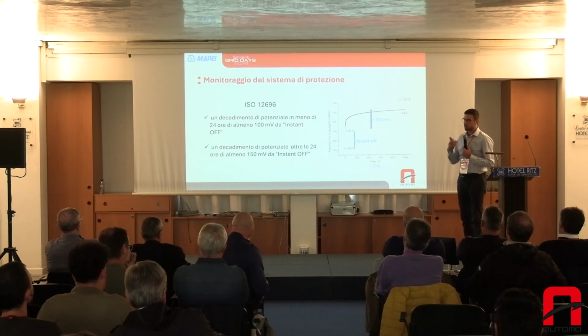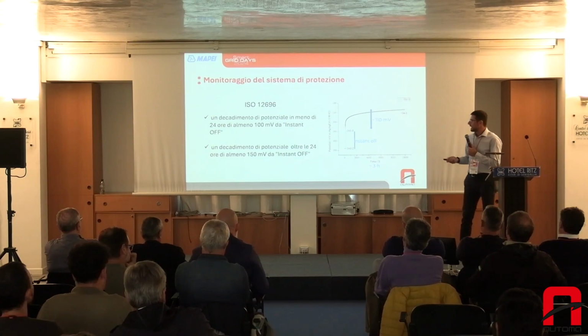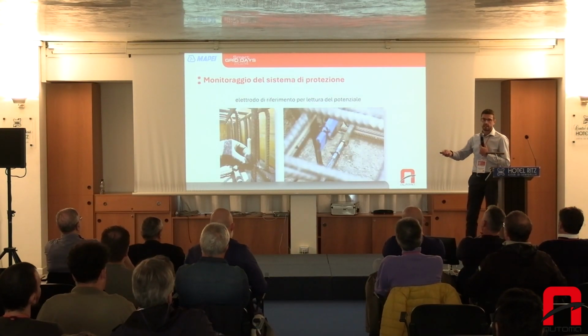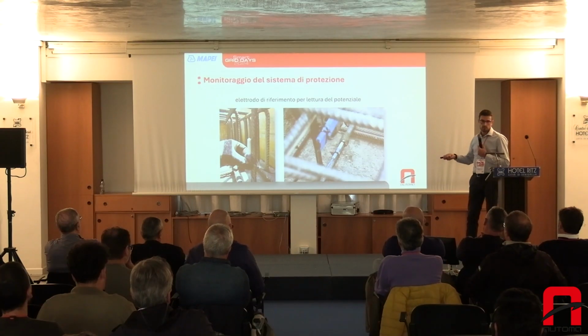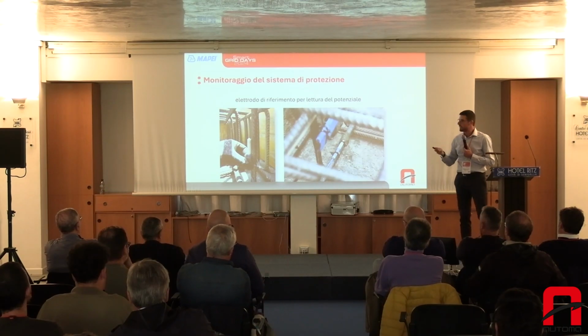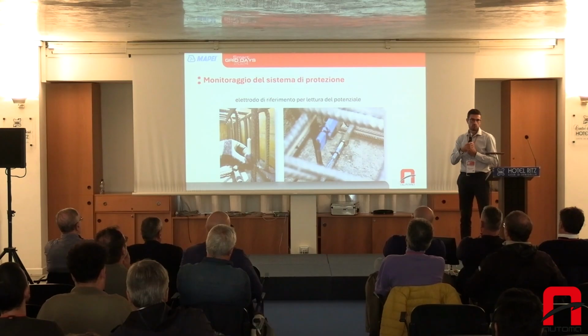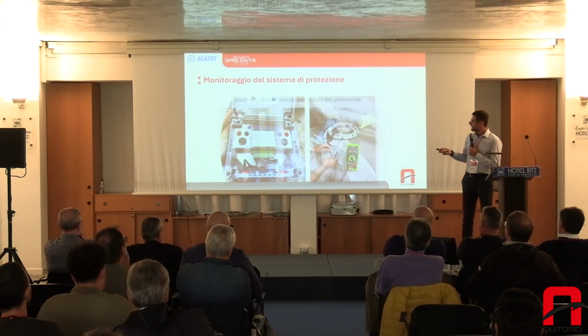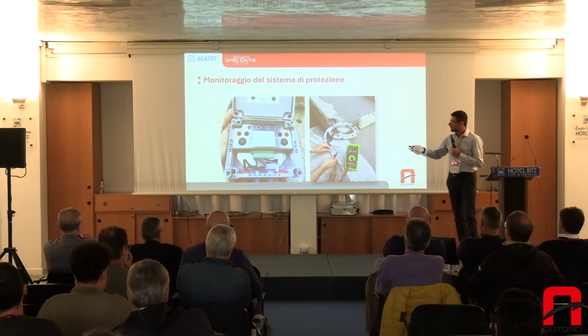If I want to monitor the system, of course, I have to include several points when installing the system. For example, I need to have a reference electrode to measure potential, and in case of external anodes, I shouldn't connect the anodes to the metal reinforcement directly. Otherwise, I will never be able to switch off the system. So I will need to identify an area of the structure where I can connect the anode and cathode externally, so that I can open the circuit and measure the depolarization. It's a very easy system.